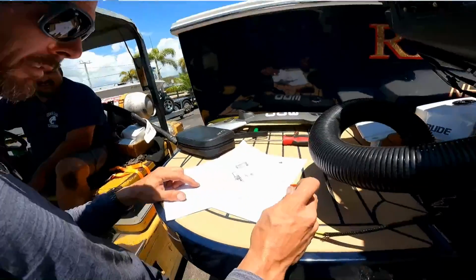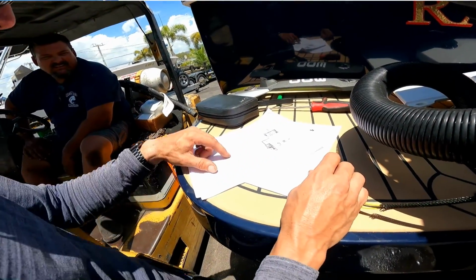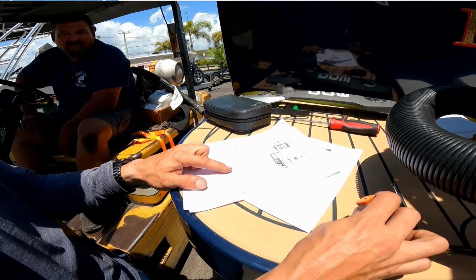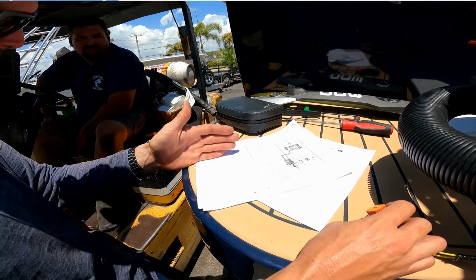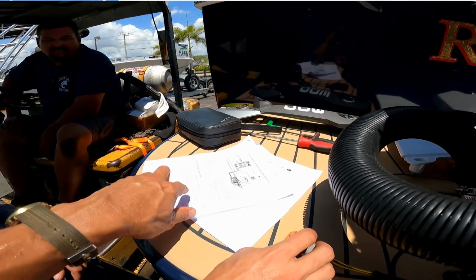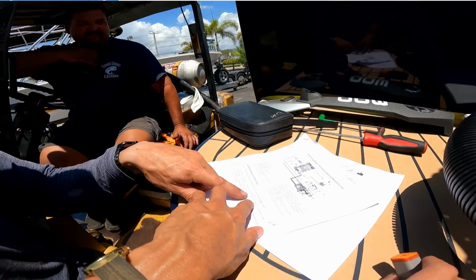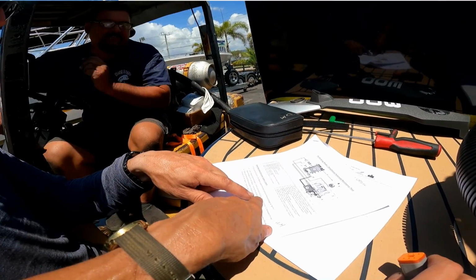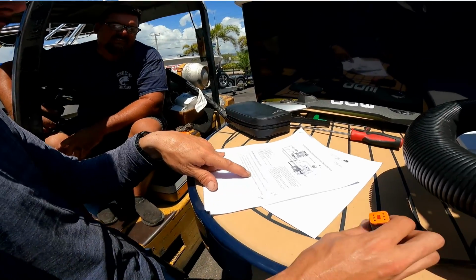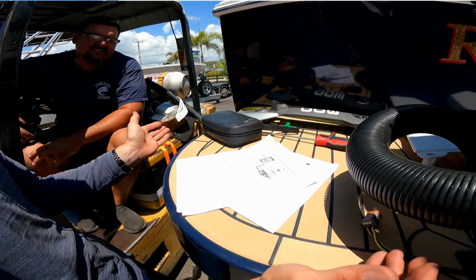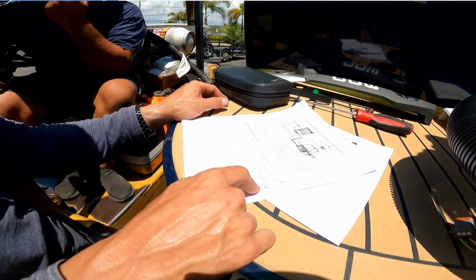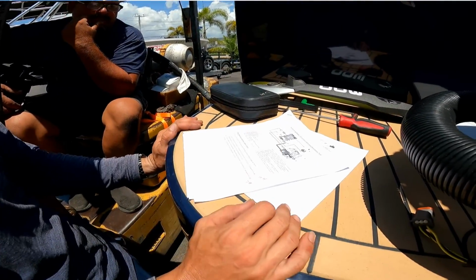So my question is, it says it's supposed to be 9.8 plus or minus 5 ohms. We're doing an ohms reading. Is that a 5.0 difference or a 0.5 difference? No, 5 ohms of difference. So this can go anywhere from 4.8 to 14.8? Correct. So it gives you such a broad window. Yeah. In the other one, you got only 7.8. So they're both within spec. Both are correct.